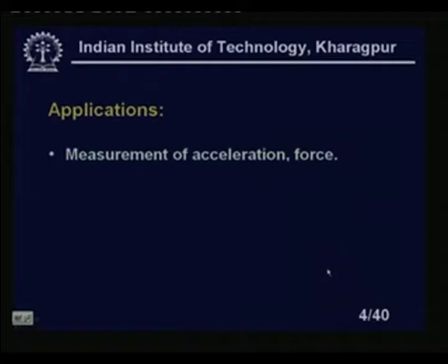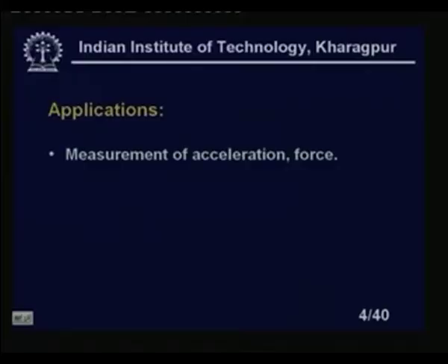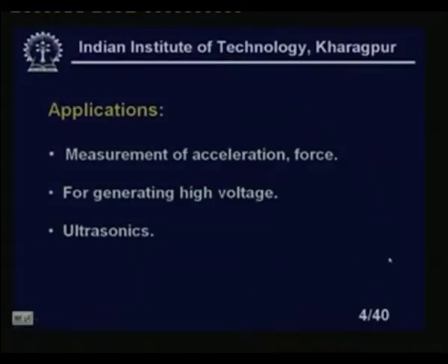Applications: measurement of acceleration and force. It is also extensively used in vibration analysis, crack detection, and thickness measurements. It is also used for generating high voltage, because momentarily it will make a very high voltage, even though the current capability is very small, if I apply sudden high pressure or impact on the piezoelectric crystals. And ultrasonics, and as I told you at the beginning of the lesson, it is also extensively used for making the crystal oscillator.